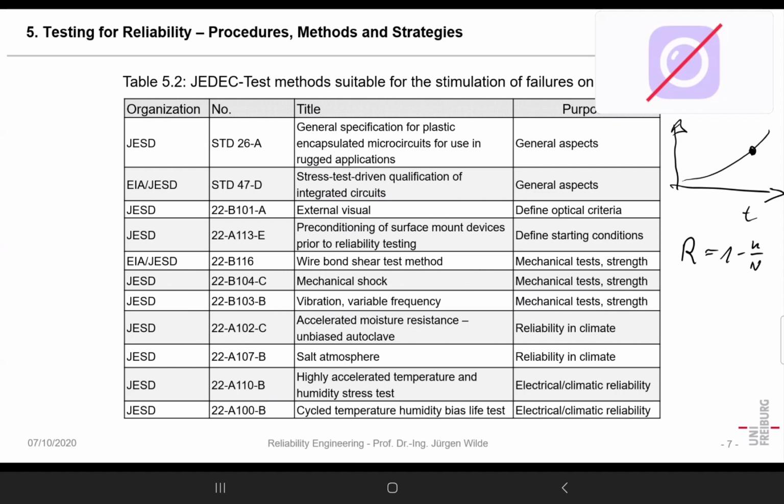The third thing is that when we have an electrolytic solution, it must be conductive, and the conduction is a result of the ions we have. So those are the three parameters in corrosion: water or a water film, electrical potential, and ions.